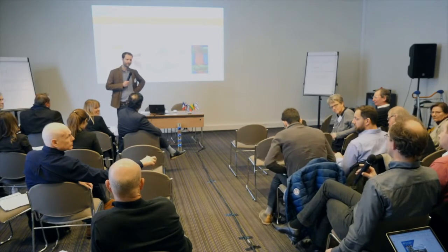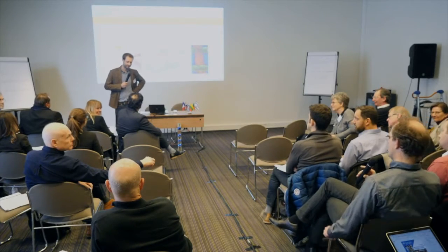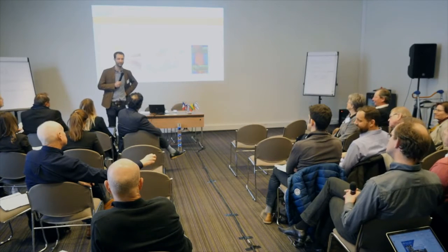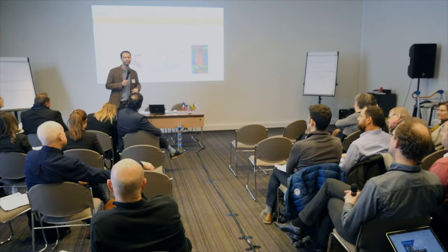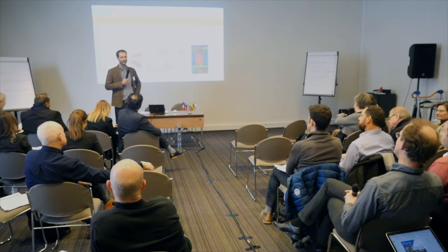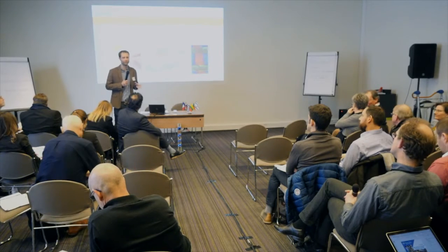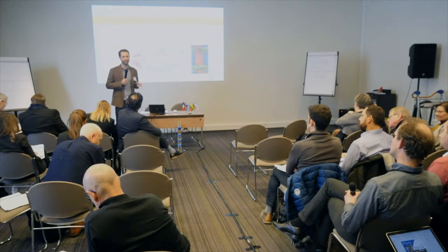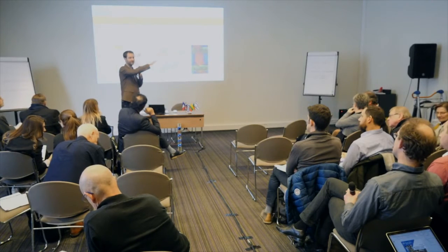I'm a bit wondering that it's not available anymore. It doesn't seem available anymore. There are two things here. There's the travel range, which is an A4, which is achievable. And there's the resolution or the repeatability of it. Obviously, if you want to have a 2-micron spatial resolution, you need to have at least a 2-micron repeatability. And to have such a good repeatability in such a long travel is actually difficult with this leverage.